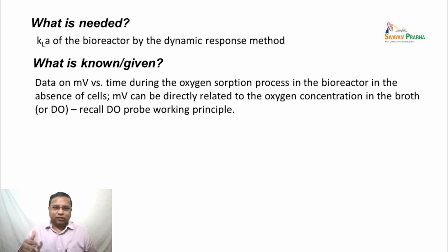The rate at which oxygen permeates through the membrane and reaches the electrochemical cell is proportional to the current that is generated by these two electrodes in the electrolyte, and therefore the oxygen level can be directly related to the current. In this example, the current is directly given instead of percentage air saturation. The current is what is actually measured, and then there is a conversion that takes place electronically in the meters available nowadays to give you air saturation by calibration. Here we will deal with millivolts themselves as direct indicators of the dissolved oxygen level, which is the bare minimum.